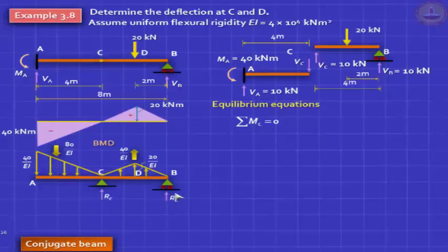We can do a little calculation. If you take moments about C, you can get RB. Let's do that. So you'll find that this into this distance gives me an anti-clockwise moment. So this distance is 2/3 of 4, so this gives me anti-clockwise, and if I take moments about C, this also gives me anti-clockwise, right?